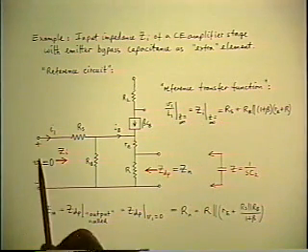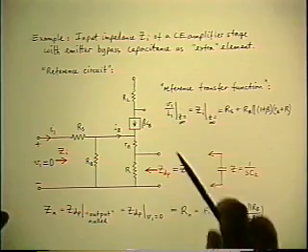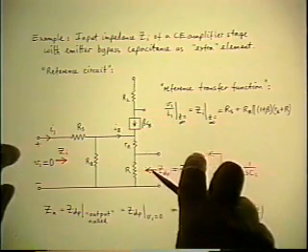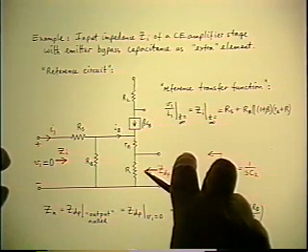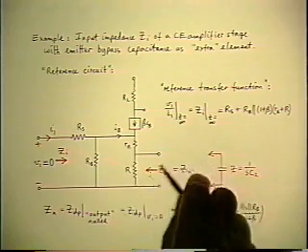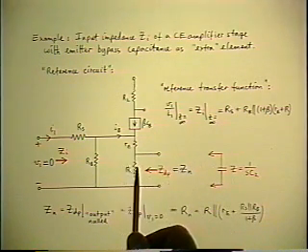So you can visualize a voltmeter hung over the input across the current source I1, and we're adjusting the I1 and the other independent source until that voltmeter hung across the current source out here goes to 0. And having established that condition, we ask, what is the resistance looking in?